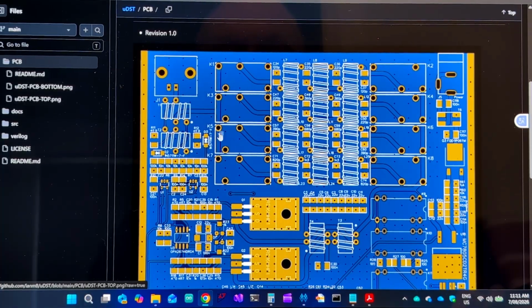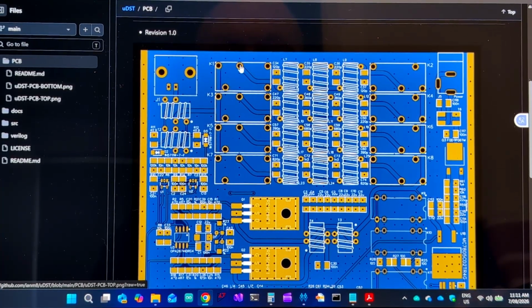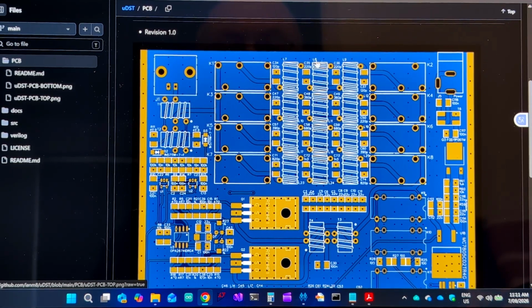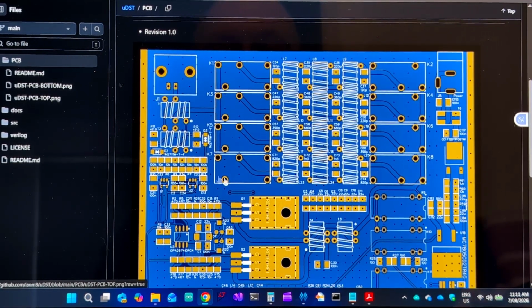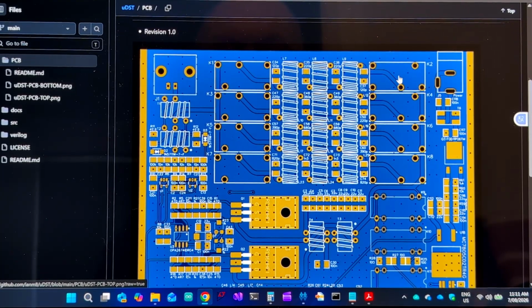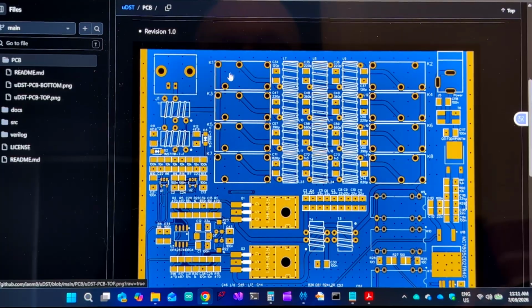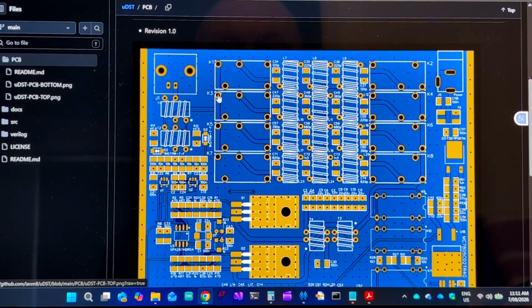But I just wanted to look at building filters on printed circuit boards, and I've seen two kinds of methods for doing this. One method leaves the top layer ground plane intact, and another method removes the top ground plane.